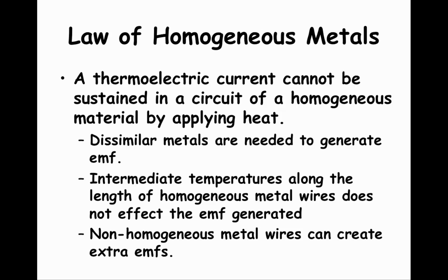Conversely though, if the wires used to make thermocouples are not homogeneous, if they are non-uniform in some way, then they might generate an electromotive force. So the manufacture and handling of thermocouples needs to meet high standards to produce uniform metal wires.